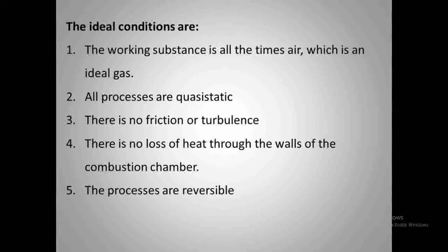And actually, what is thermal efficiency? We learned that already in the last class. What is the thermal efficiency of an engine? It is actually 1 minus QL by QH. What are QL and QH? QL is the heat rejected by the system to the low temperature reservoir, and QH is the heat taken by the system from the high temperature reservoir. So this is the efficiency. We have to calculate here the efficiency of an Otto engine or a gasoline engine. So what are the parameters?